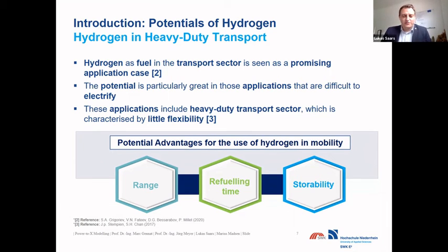so that this advantage really is an advantage. Then to refueling time, depending on the pressure in the hydrogen storage tank, fuel cell buses can be refueled much faster than electric buses can be charged. However, this argument can only be used if the range of the electric bus is not sufficient to make the bus cycles. Often the buses are parked in depot at night anyway and can be charged without any problems, because overnight there are long standing times and there's no problem with charging the buses.